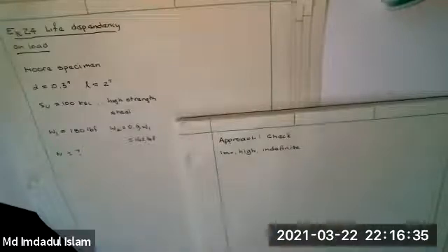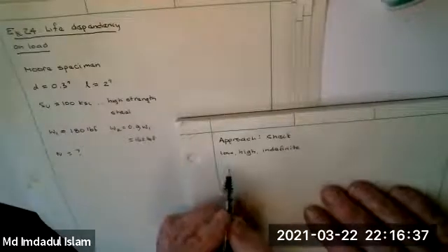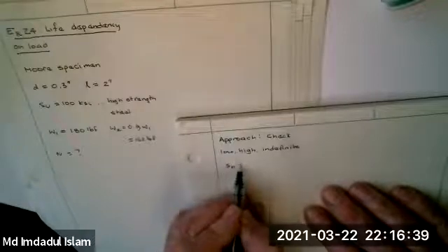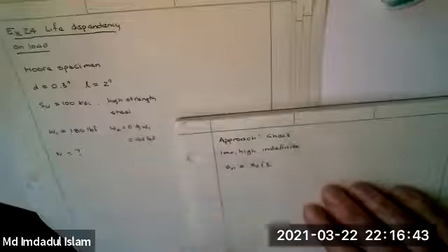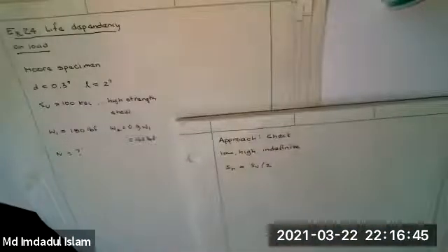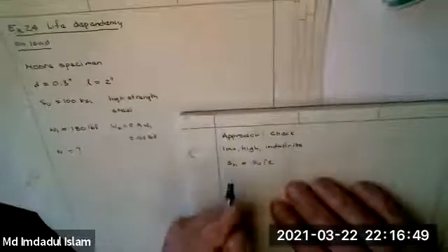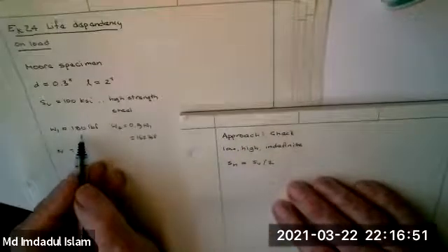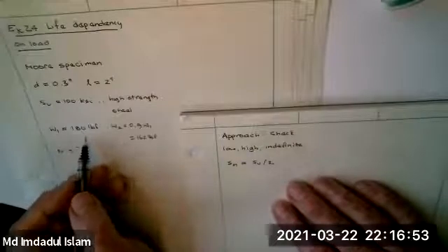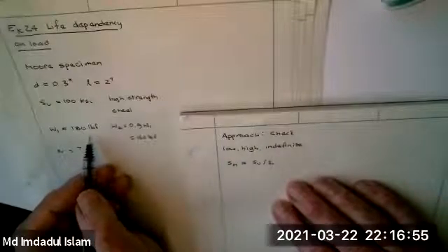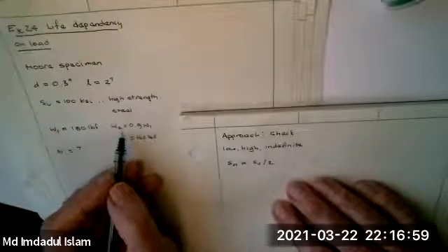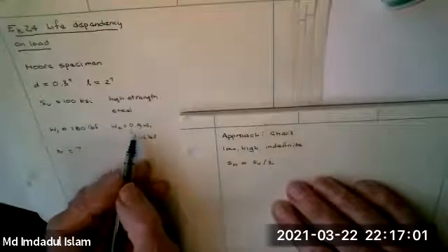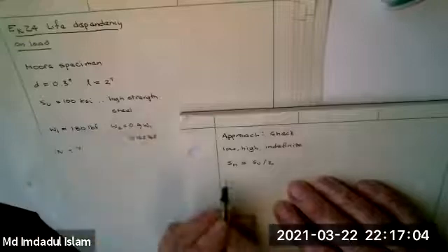The other thing we're going to do is we're not given SN. So the standard thing we do is we're going to take SN as SU divided by 2. And that's what you do automatically. Well, if we do the higher weight, we'll see if it's in high cycle, this must be high or indefinite. Okay, it's got a lower load.